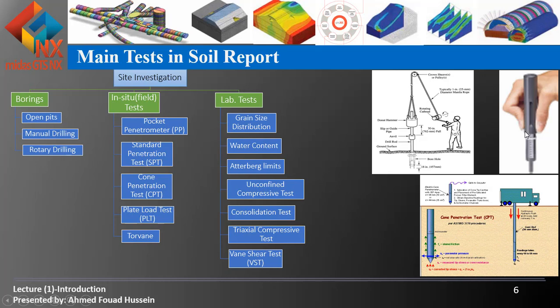This is the pocket penetrometer test, and it's a very simple test to obtain the cohesion of the clay soil. You just push this tip into the clay soil, and we have a graduated scale here which refers to the strength of the clay soil.